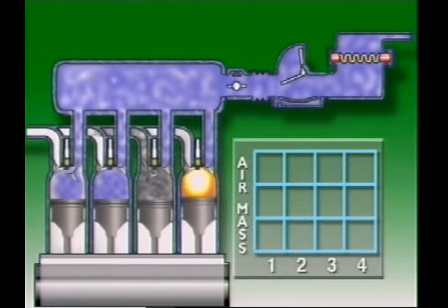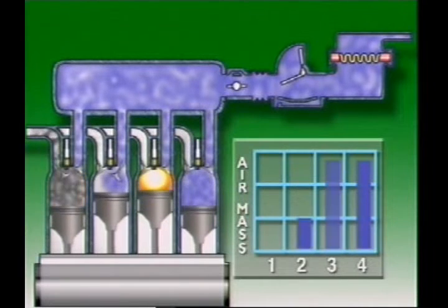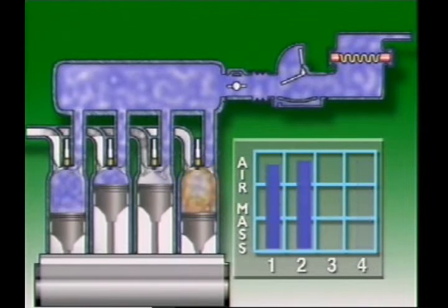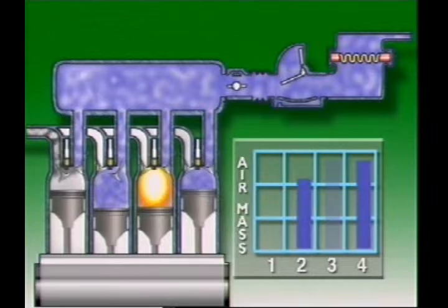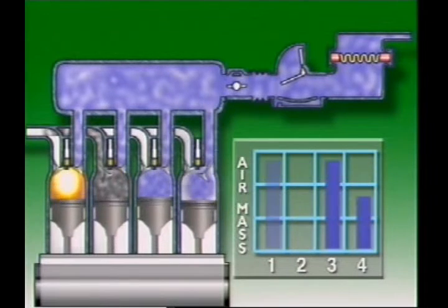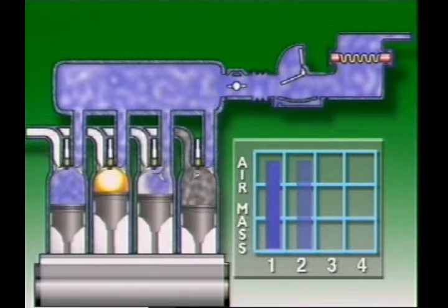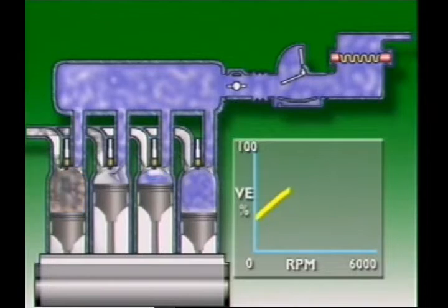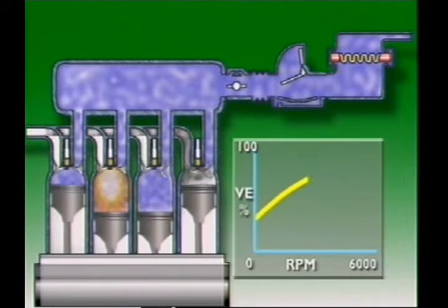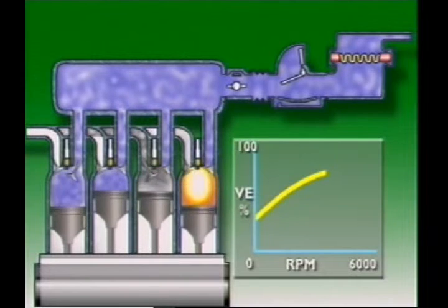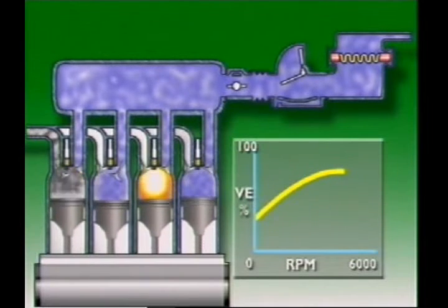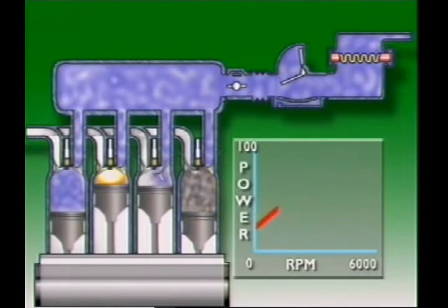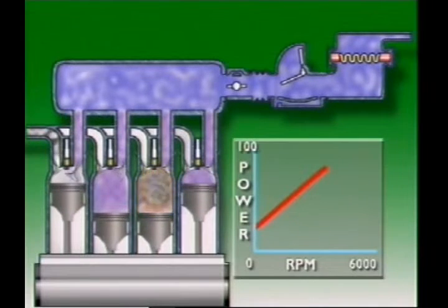The design of the intake system determines how large an air mass can be drawn into a cylinder at any given engine RPM. This is where most advantage can be taken of electronic fuel injection, since it can achieve exactly uniform distribution of the air delivered to the cylinders. With unobstructed passages to each cylinder, the cylinder fills with air as efficiently as possible. The breathing of the engine, or its volumetric efficiency, is improved. The more air crammed into the cylinder, the denser the air-fuel mixture when ignition occurs. This increases the thrust on the piston and increases engine power output too.